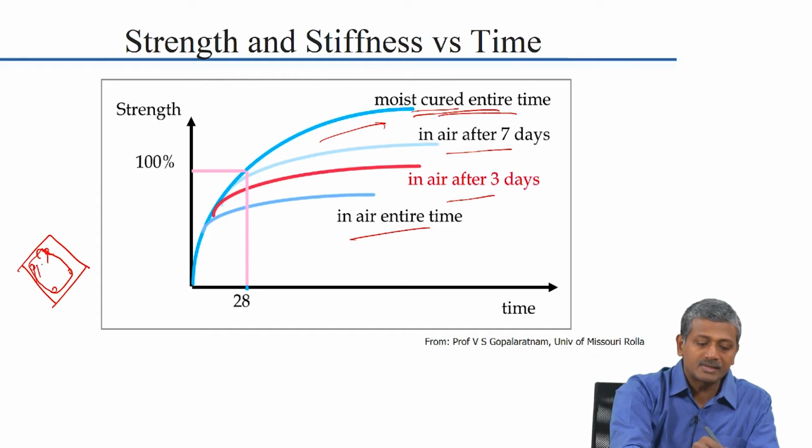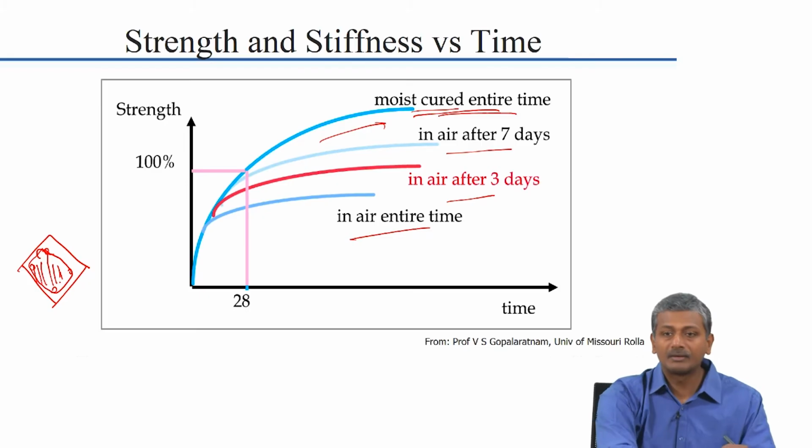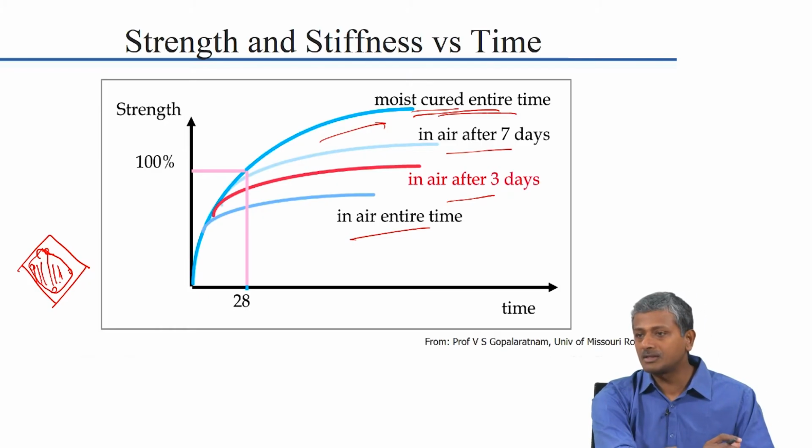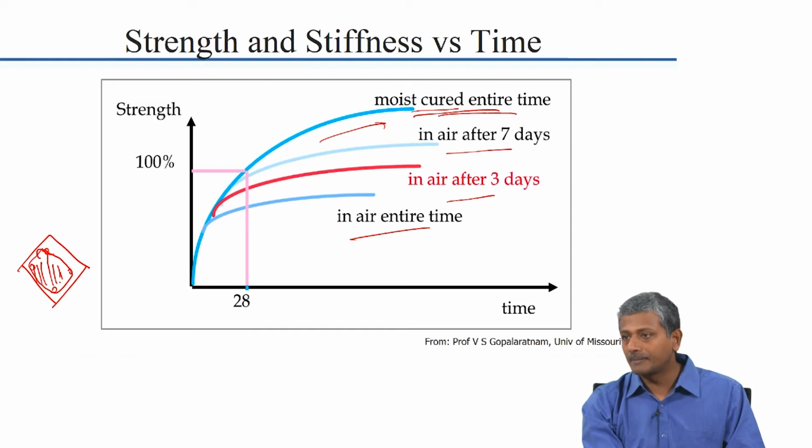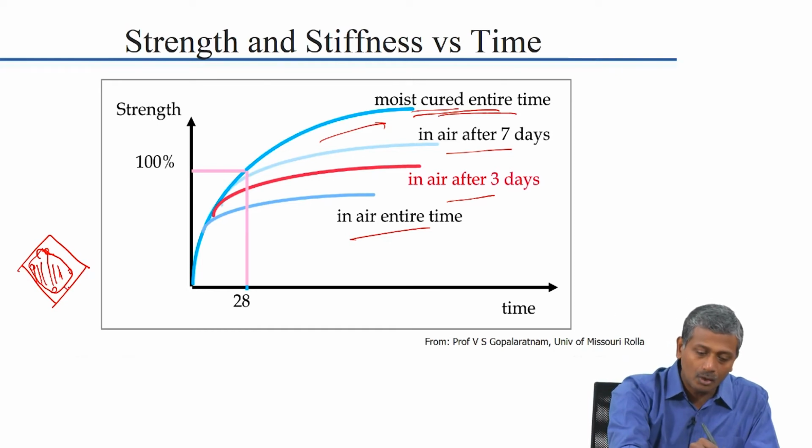The concrete that is inside the reinforcing bars, which is in the heart of your column, is truly not being subjected to any drying. So, the water-cement ratio that you would have used in that concrete would be maintained throughout anyway, because the cover to the column can vary as much as 25 to 75 millimeters, right.